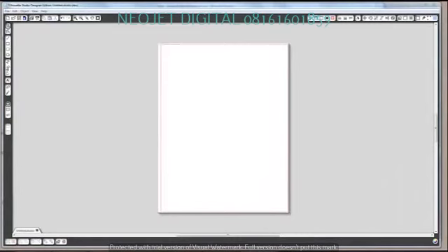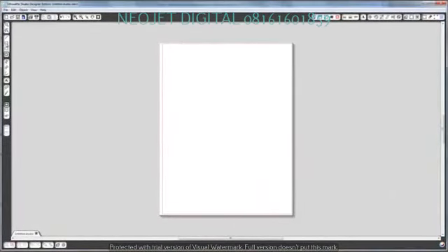Silhouette Studio includes several tools used to draw simple shapes like circles, rectangles, and lines. Just click on the tool you want to use and then click and drag to draw your shape. Hold down the Shift key while drawing a rectangle to draw a perfect square. Holding Shift while drawing an ellipse will create a perfect circle. Some objects have more control points that can be used to alter their look. Click and drag them to see what they all do.